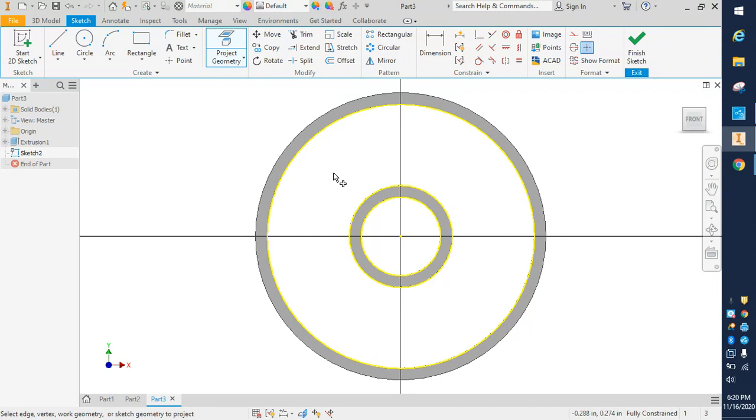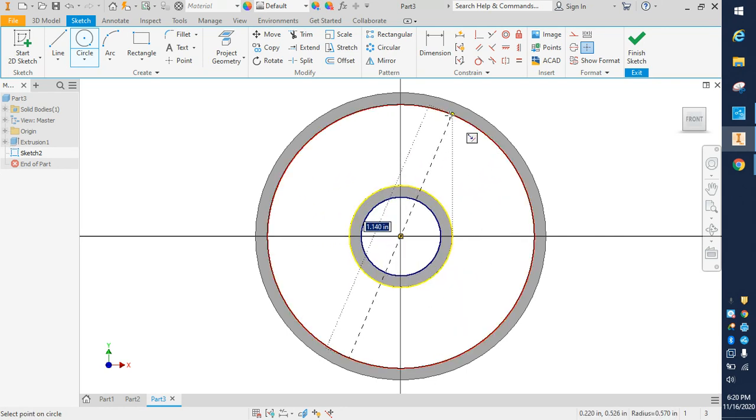If I study my drawing close enough, I'll get that right. So from there, we haven't really drawn anything yet. We've just said, yeah, there's a line there that we can click into. If we don't do that, we may not be able to click into that. So take our circle tool and we're going to click right out to, and it snaps right into place. Take another from the center, we'll snap into place right there. Okay.